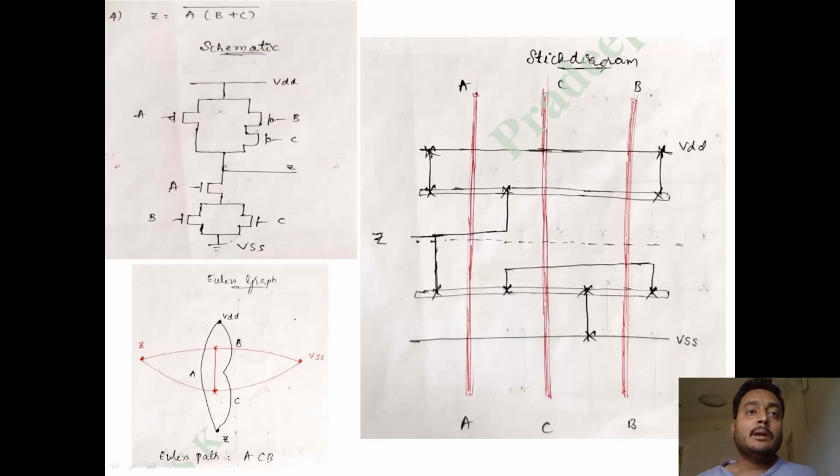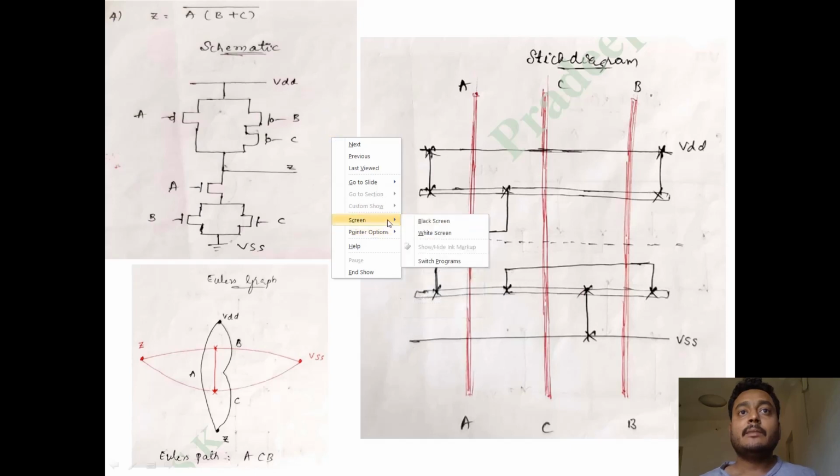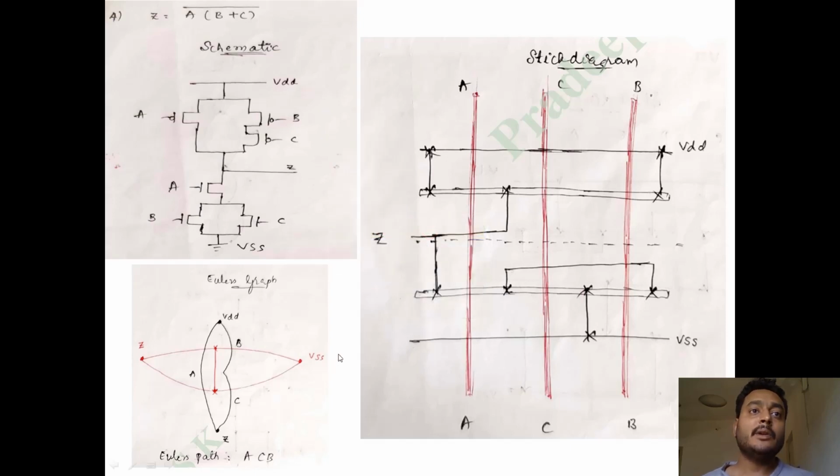Okay, right. So this is the thing, and so here what I have done is, again, first thing is I have drawn a VDD line. This is how you can write it using just a pen. Okay, so the VDD line. Then I will draw the VSS line. Then I will draw the demarcation line. Then I will draw the P substrate and N substrate. Okay. So then I will draw three polysilicon lines because I have three variables. Three variables, three polysilicon lines.